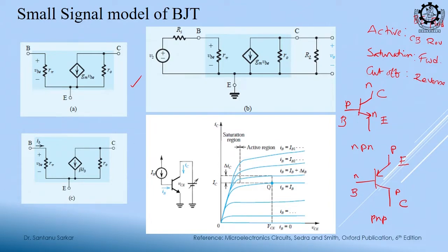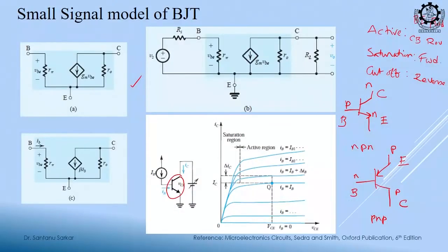Now, you see I have a transistor. Just as you said, this is a symbol, right. So, we have an equivalent mathematical model for this. So, this is our model. What is my input side? This is my input side, base to emitter. So, there is a resistance, just like you think of your amplifier, input to output, on the input side there is a resistance. This resistance is nothing but R pi.